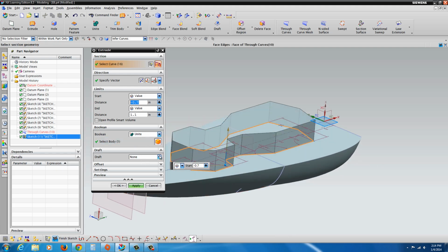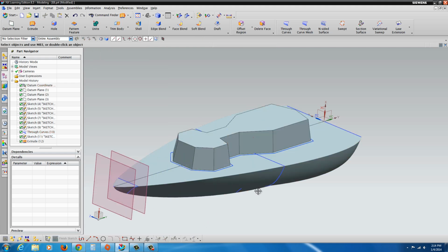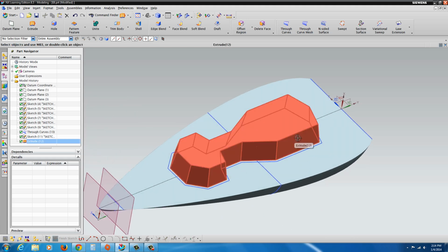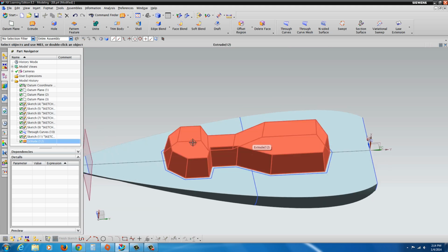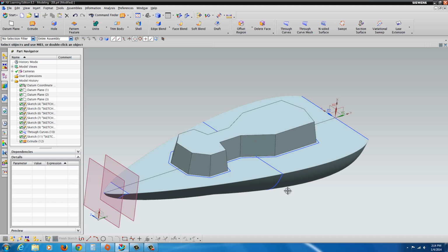And then also a couple things you can do. You can add draft, start, hit OK. Then it will merge with it. And really, it's just a matter of building on top of that. And again, always selecting that plane there. Or you could select this surface now because it's nice and flat, or any of the side faces to add whatever you need. And that concludes this exercise.